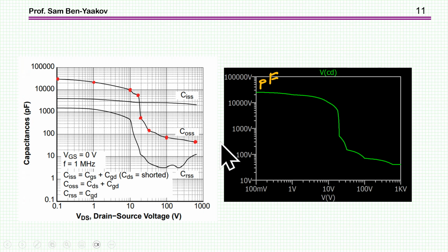So first thing I'm showing here is the matching of this table, or the fitting of the data to the table, and the actual data. You see the fitting is pretty good, except here the interpolation by LTspice is not actually following this, so it's a little bit different, but in general it's a pretty good fit. You see that the value here is about the same, and also the value here, and I've checked all the other points, they are pretty good.